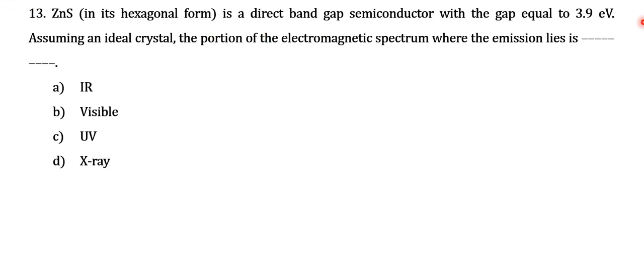So first you have to find the lambda value. There was a relationship I told you in the last class between Eg and lambda. If anyone remembers, it is Eg or E is equal to 1240 by lambda, so you will get lambda in nanometer.